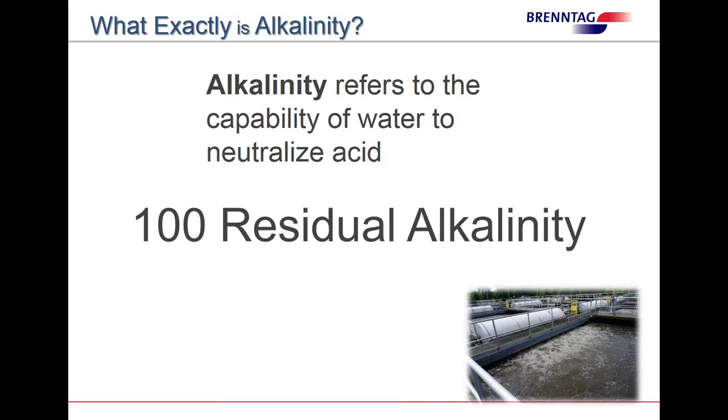And I've solved tons and tons of problems in wastewater treatment plants with just one of these little Hach test kits of alkalinity strips in my front pocket. Check the alkalinity, and it is nothing. And that's a problem. Zero alkalinity equals zero bugs. Okay?